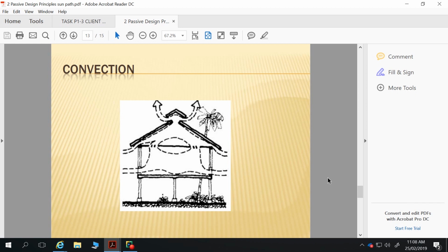The reason they're called Dutch gables is because they were first used in South Africa by the Dutch settling there from a fairly cool climate. South Africa is quite a warm climate, and one way of getting that passive air conditioning was via the design of the Dutch gable. Probably 99% of Dutch gables built onto buildings now are just aesthetic, about creating some articulation in the roof space rather than providing ventilation. But some Dutch gables you see about the place still have those little vented louvers in the top working like that.